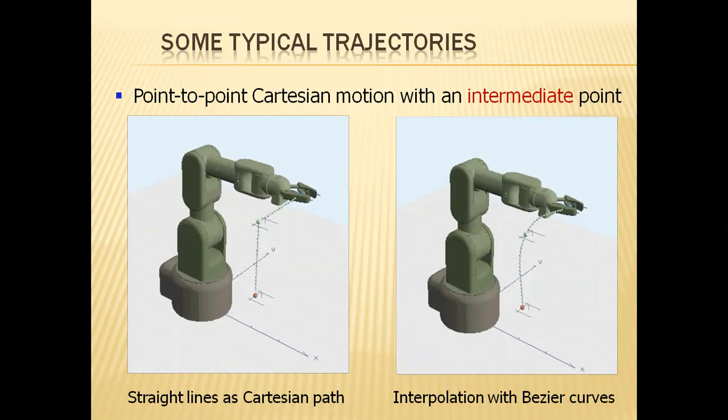For curvilinear positions, the revolution or rotations need to be considered. And for that, almost all the articulated kind of robots are used here. This articulated robot will traverse or generate interpolation, that is nothing but circular interpolation, or circular motions related to the given dimensional accuracies.